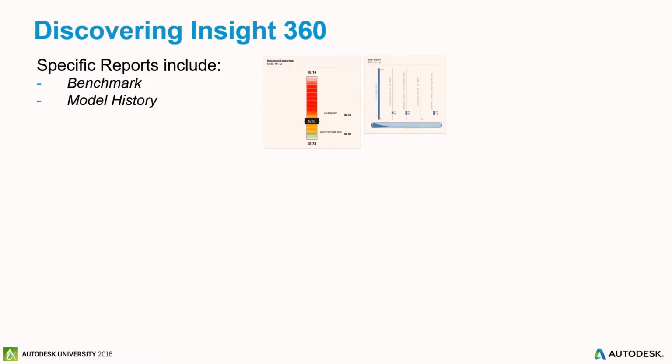You have a model history. I can make several runs, and I can examine individual runs. So as I go back and I start looking at solar and lighting analysis and start saying, okay, what happens if I introduce PV into this? How big of an impact is that going to have on the cost mean? And so you can actually look at different runs, and you see that little bar on the bottom that goes across. It looks like it's getting skinny. I like the skinny one. I don't like the big one. That means we're burning up a lot of energy.